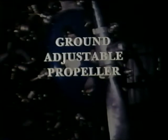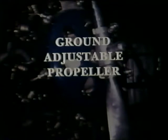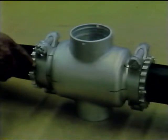Ground-adjustable propellers are designed so that their blade angle can be adjusted on the ground to give the desired performance. The propeller is designed so that the blades can be rotated in the hub to change the blade angle. The hub is held together with clamps or bolts to prevent the blades from rotating during operation.